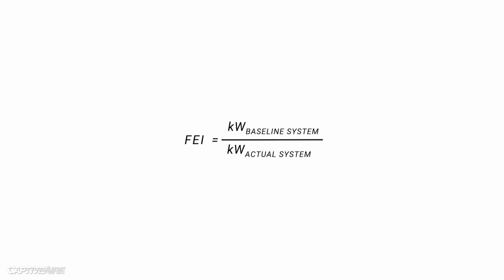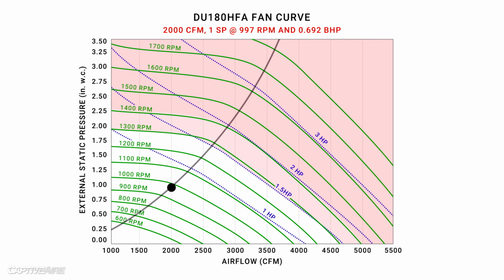So in order to know this number and correctly plot it in our charts, we have to account for a bunch of factors, because in the end we have to know just how much power the fan and motor combination will draw under all possible conditions. We look at things such as the efficiency of the motor, whether or not there's a use of a VFD, if it's direct drive or not direct drive. We also look at the fan types, and there's a lot that goes into that.